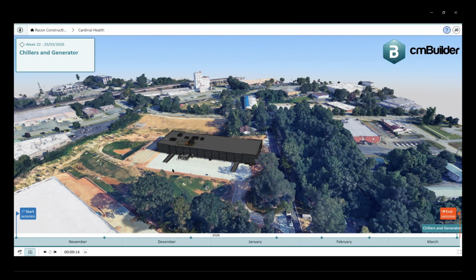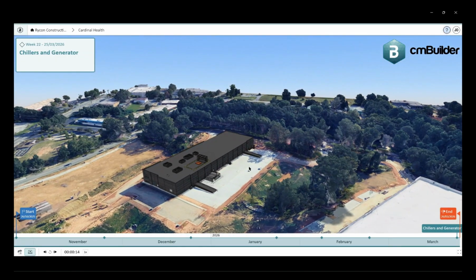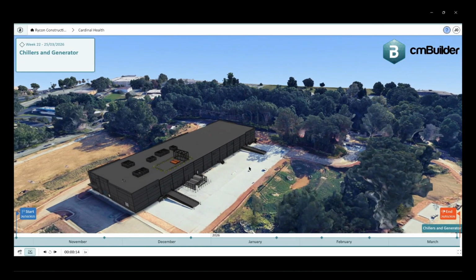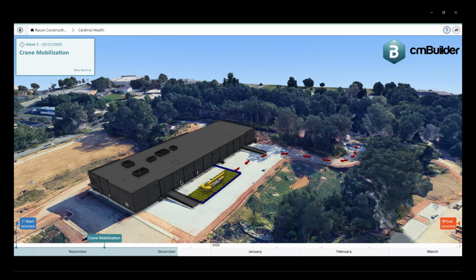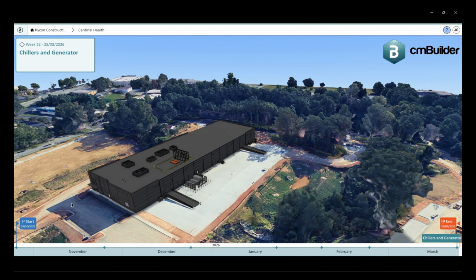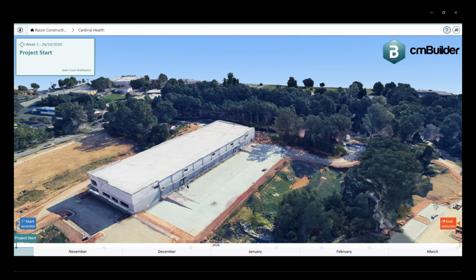So realistically, through 2 meetings with them, they were able to help me set this up, and we were able to even integrate our Revizto model, as you can see here, onto the Google Earth site. So we have access to the entire site, and we're able to see where we can bring a crane in. See, this was a potential spot. Just bring it in through the back there, setting it all up, and you see you can animate the crane right there, how it was actually doing the cyclotron drop. You can animate having the workers on the roof, animate the setup of the crane, being pulled onto site, being pulled off a site. And this is just one scenario. So this was for the cyclotron drop.